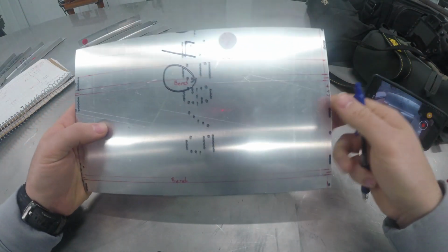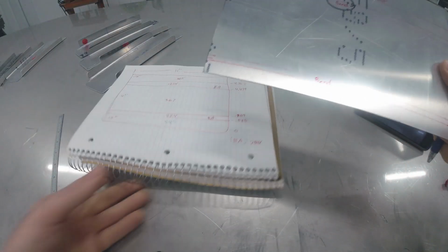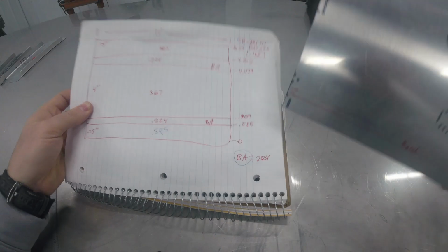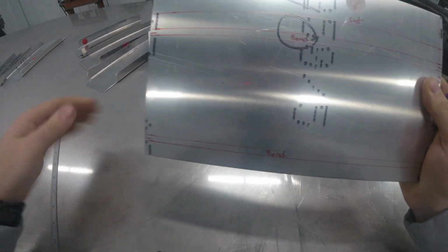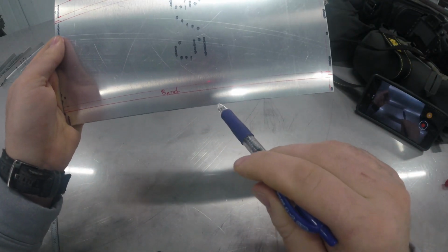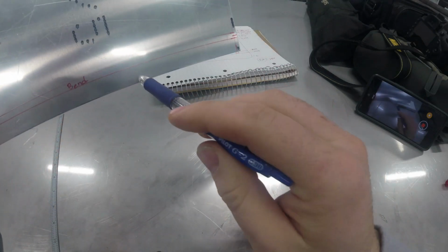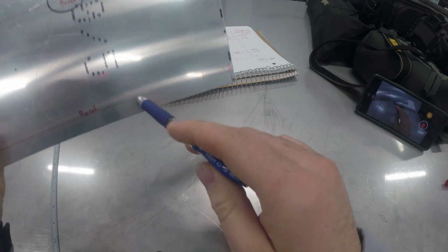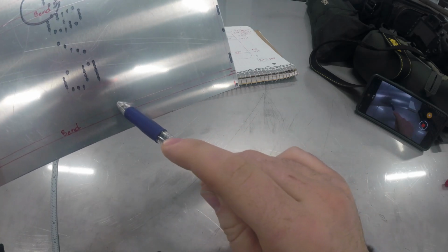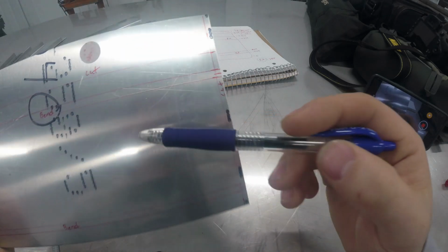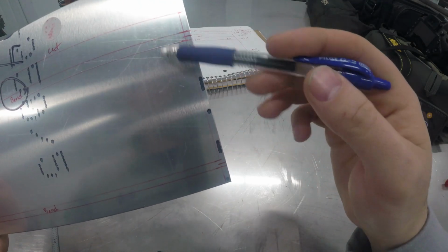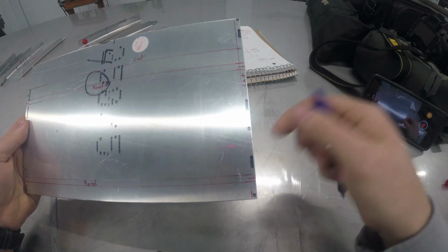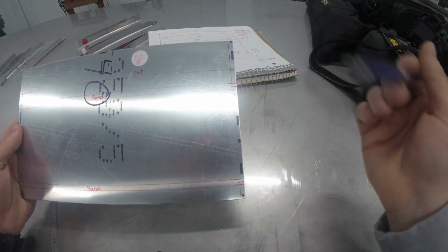After that, I went ahead and took all of our measurements on this side and transferred them to our sheet again. So just used this as my 0 reference, and then went up with it. So 0.585 inches on the bottom, then 0.809 inches, and then we've got our long flat here. I don't know how well you can see this on the camera. And then our next bend, and then our cut line, obviously.